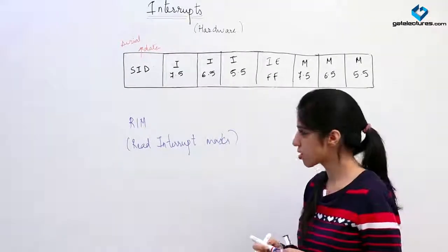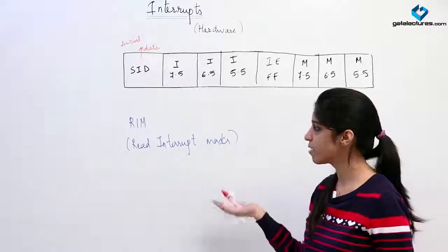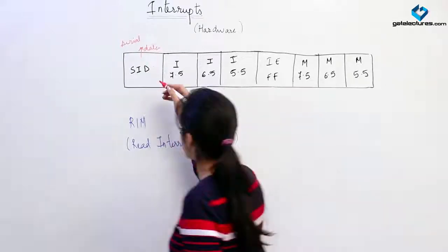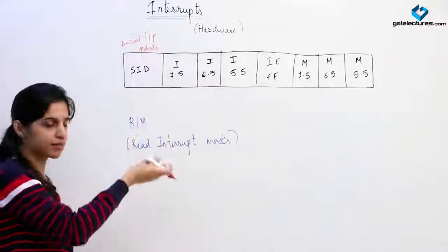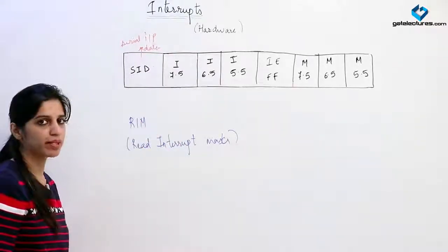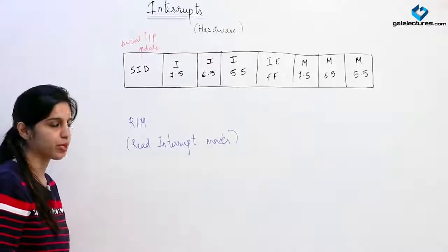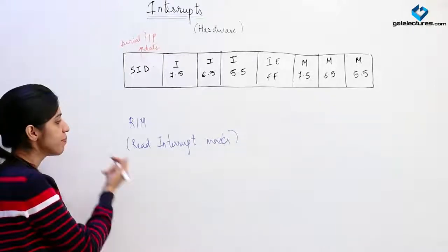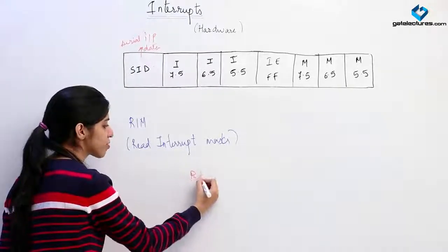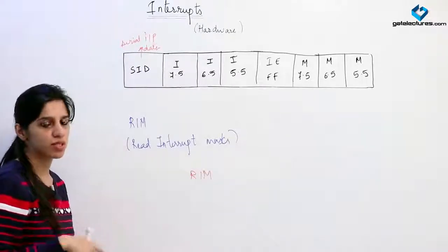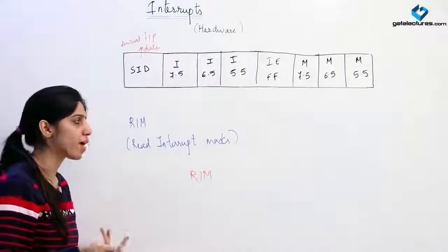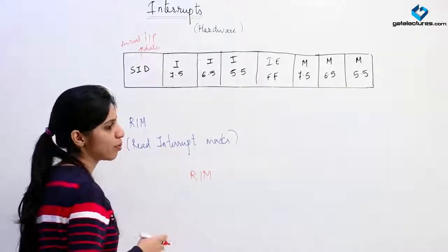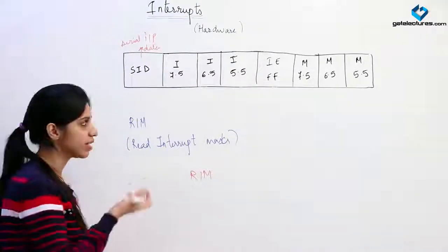Previously we learned the instruction SIM, which sets interrupt mask. This reads interrupt mask. The default register here also is going to be the accumulator. It is going to read the status from the accumulator only. Whenever you give this instruction RIM, the value of the accumulator will be displayed. It tells you what is stored in the accumulator, and accordingly you can interpret it.